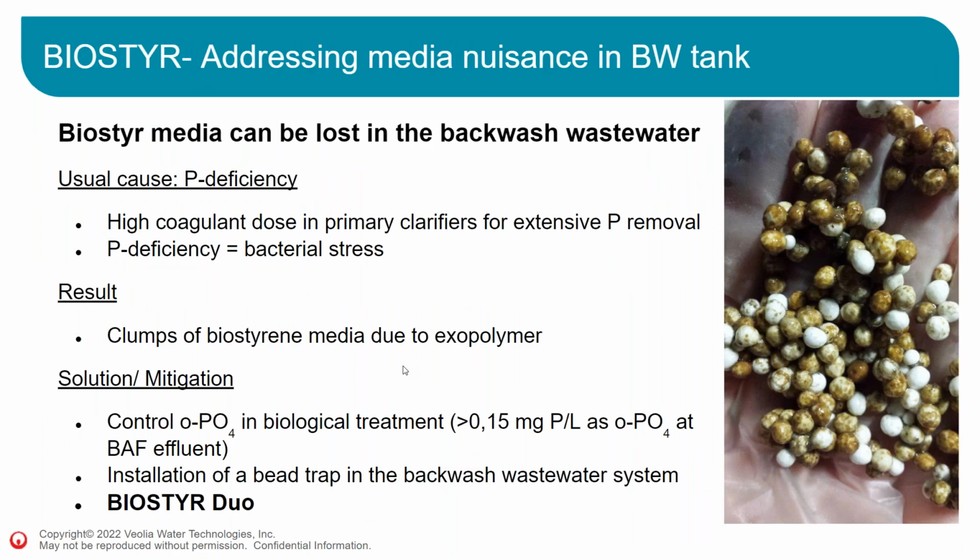So Biostyr. You might have heard that some people are concerned about losing some media during backwashes into the backwash tanks, and getting the beads out of the backwash tanks is not an easy task. Most of the time, this is due to bacterial stress. What could cause a bacterial stress? One of the causes we've seen often is a lack of phosphorus. There's not enough phosphorus in the Biostyr. The result is the bacteria are stressed. They create exopolymers, and these exopolymers create clumps of biostyrene that will be dragged through the backwash.